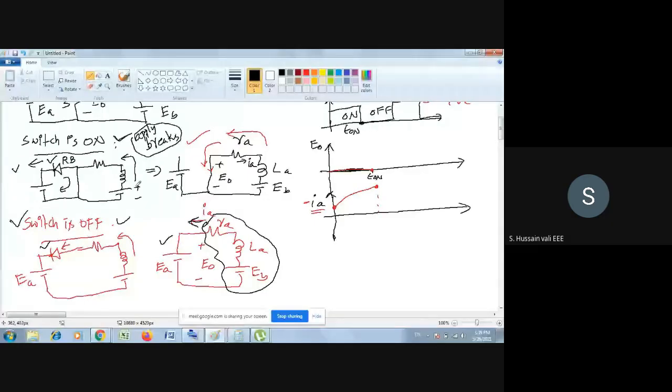Let me tell you one thing. We are studying the chopper. The first quadrant chopper we studied last class. Now we will study the second quadrant chopper, and then the fourth quadrant chopper also. Actually, you generally use the fourth quadrant chopper in motors, not the first or the second quadrant. Why are you using the chopper? I told you already that you use the chopper to control the DC motor, whether a separately excited, series or shunt motor. Chopper is one of the options.